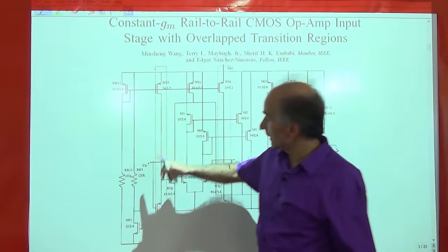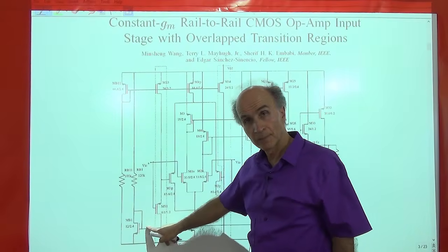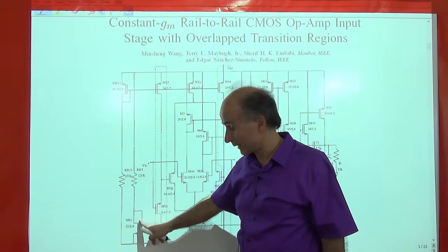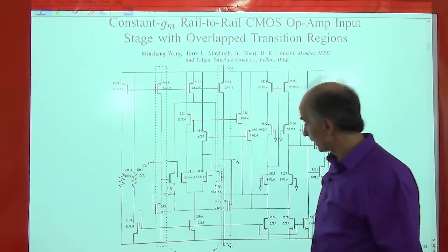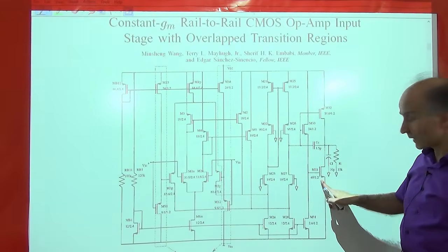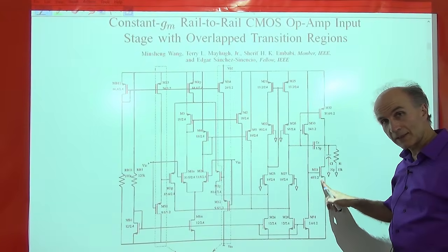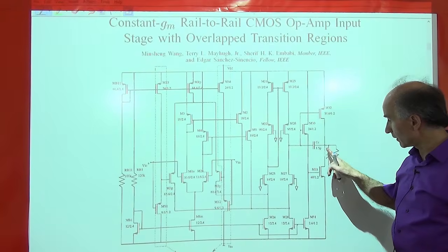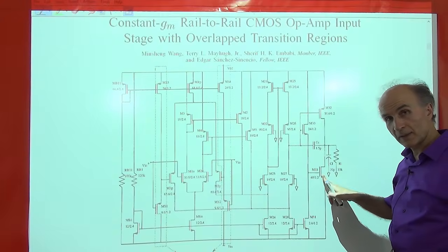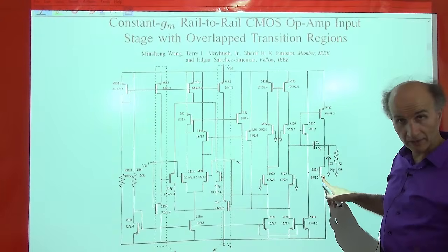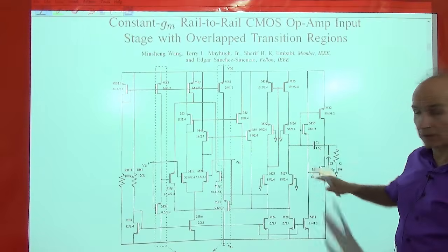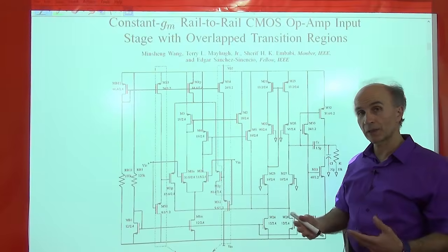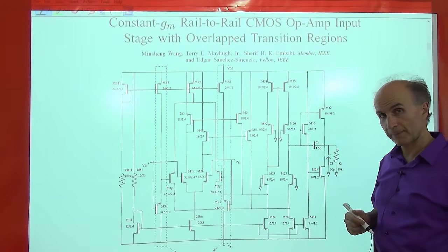We can see a diode-connected device here. Again, the drain and the gate are connected. So that's a diode-connected MOS device. We don't exactly know what it's doing, but it's there. Then this NMOS device receives a signal at the gate with the source grounded, and the signal comes out of the drain. So this is a common source stage. So that's not bad. But of course, there's a lot of stuff here. So we have to go farther, analyze more circuits, understand new circuits before we can understand something like this.